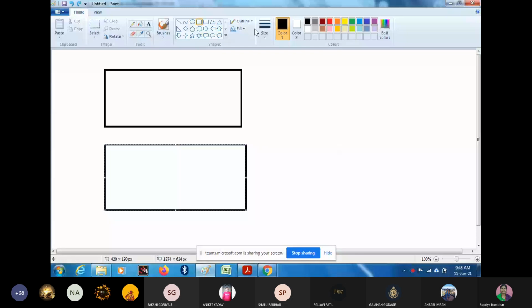The intersection point of those two planes we consider as a reference point or reference line. Here, above this reference line there is the vertical plane, remember, and below this there is the horizontal plane according to the first angle method of projection.